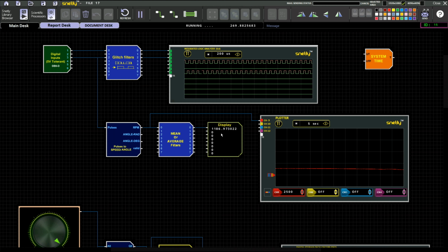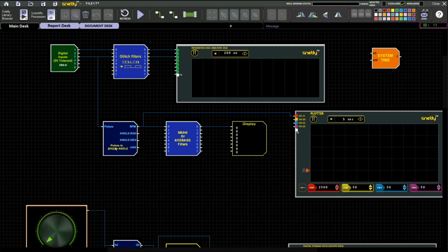This is the complete model for designing the motor to run in open loop condition for a 3-phase induction motor drive with V/F control logic. Here we are going to make some modifications for the closed loop speed control. Let me stop the system and we will change the required blocks for the closed loop control. Here we are going for the PI control logic.